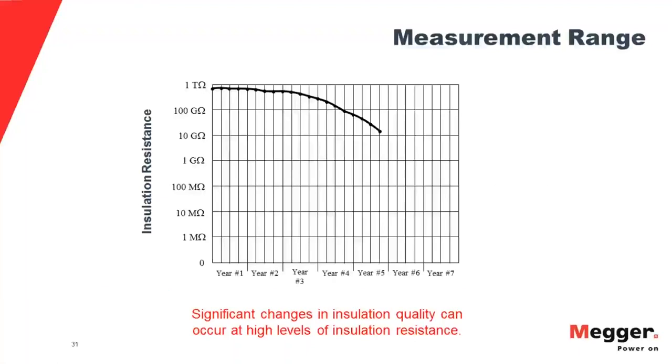One of the reasons here would be what we show you on this graph. If you were keeping maintenance records, and you had a tester that only went to 1 or 2 gigohms, you wouldn't be able to construct a graph like this. And this is kind of a distant early warning. What this is telling you in this particular case is that insulation resistance is dropping rather rapidly.